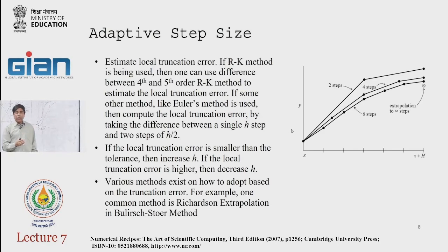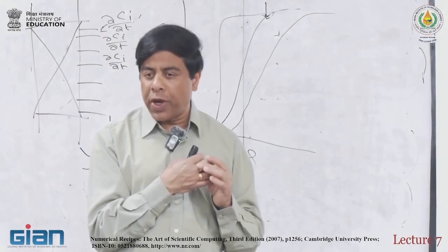How do you decide the end of all time steps? So I'll show you where the tolerances are. Aspen by default, I think, has 1e minus 7 specified as the tolerance.